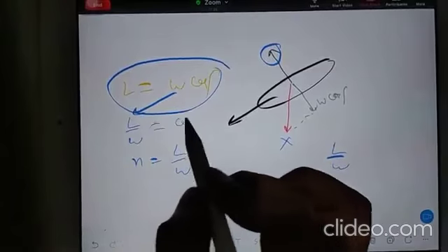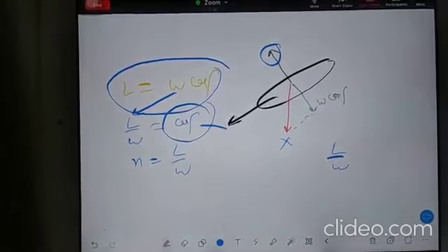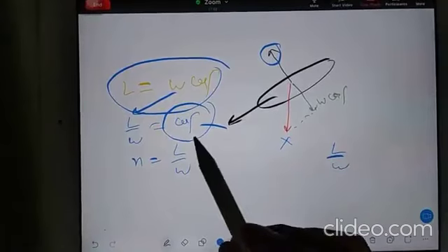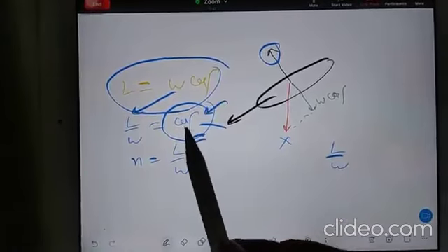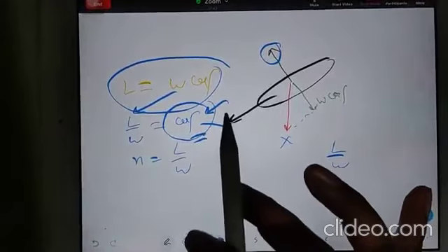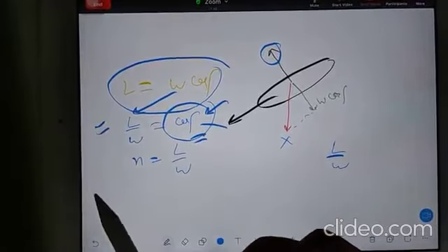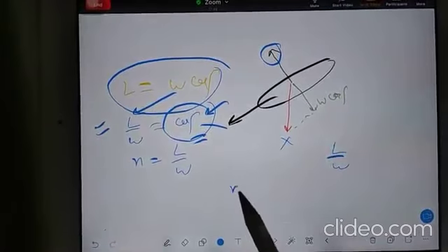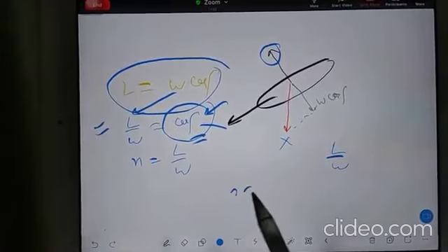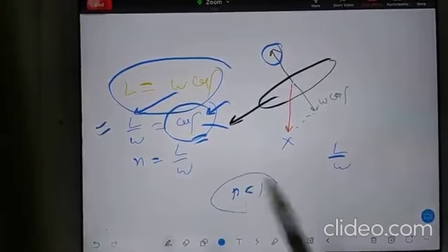So from this equation, finding lift by weight, send the weight down. Lift by weight is equal to cos gamma. Cos gamma will always be less than 1 in case of gliding. So this load factor is always less than 1. Okay, so less than 1 is the correct option.